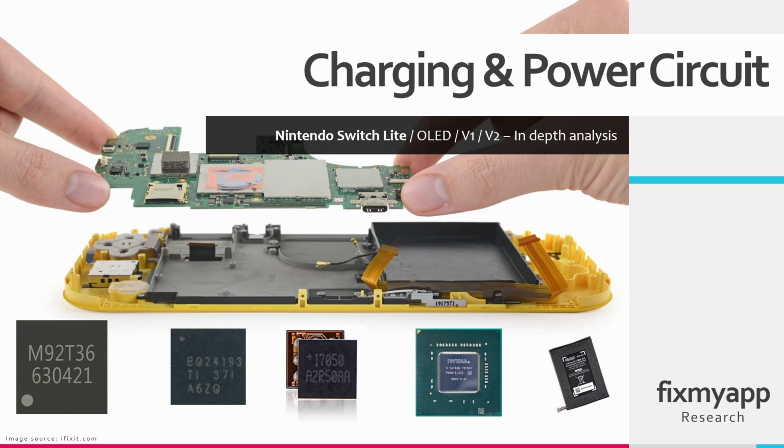Nintendo Switches use different integrated circuits like the BQ charging IC, the USB-C power delivery controller, the fuel gauge IC and also multiple power management ICs. I am going to explain how these ICs operate and how they communicate with the APU, to give a better understanding when you have to troubleshoot this circuit. Most of the time when you have a no power condition, one of these ICs could be faulty.